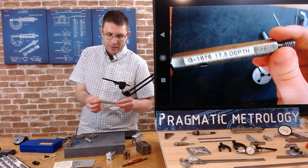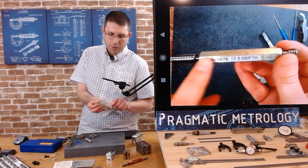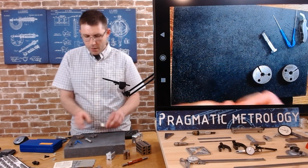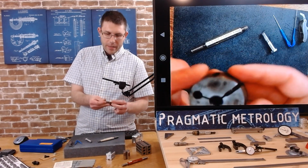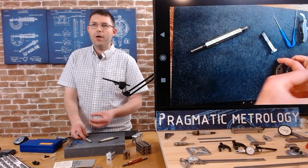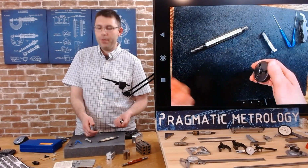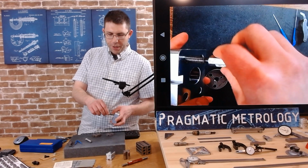This body has gotten so used up and worn that it's pretty hard to even see the Go and the NoGo, and it's under this label. But right away you can see the Go side is usually bigger than the NoGo side. For the rings, you're going to have a Go ring and a NoGo ring, and it's the same thing. The Go ring should go on your part, the NoGo ring should not. It's the same as plug gauges. When you're checking holes, you have a Go pin and a NoGo pin. It's the same application. So very quickly I'll demonstrate.